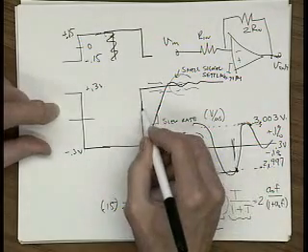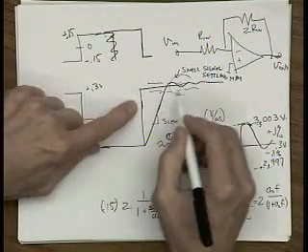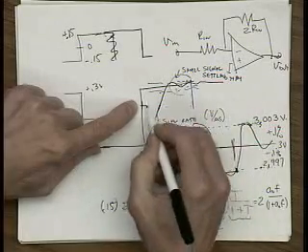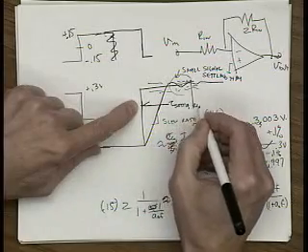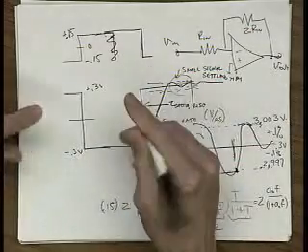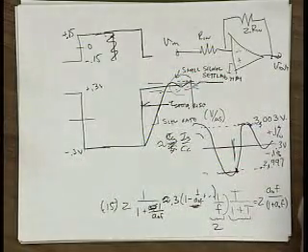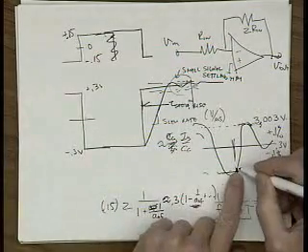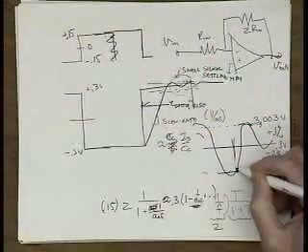So it's the time from t equals 0, when the input makes a change, to the point where it finally gets inside the error bars, right about there. So this is t settle, kind of rise time. This is the rise time of the output. There'll be another one for the fall time, because the circuits don't necessarily have to be perfectly symmetrical, especially in the nonlinear part of the response. So you look to see where it enters that error bar, and once it's there, you call that settled out, and you measure the time from t equals 0 when you did your input.